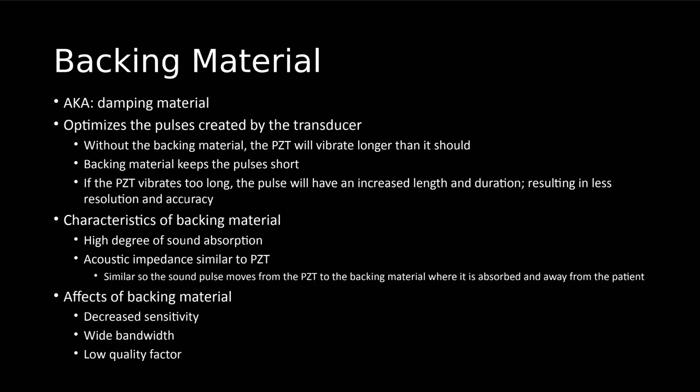And it's going to have an acoustic impedance similar to the PZT, so it is still going to allow those pulses to move easily from that active element, that PZT, to the backing material, where it's going to be absorbed and kind of given instruction on what it can do. Now, there are some consequences of having backing material. So yes, we don't want our sound wave to just vibrate uncontrollably or longer than we need it to.